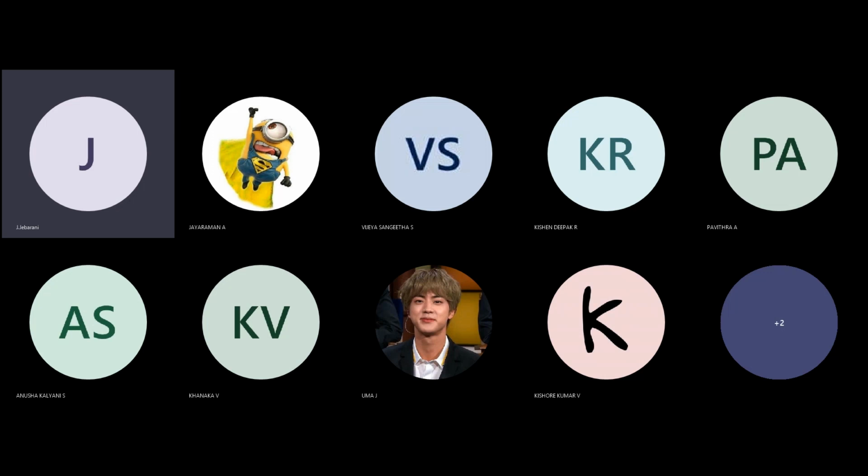Due to that, the water injection pressure is very high when compared with melt pressure to push it to the end of fill. So at this point, the transition from resin injection to water injection may cause a hesitation mark on the surface of the part. So a finish may not be feasible. Also, the material at the end of the shot is likely to form a thicker section that could lengthen the cycle time. So this is the short shot process.